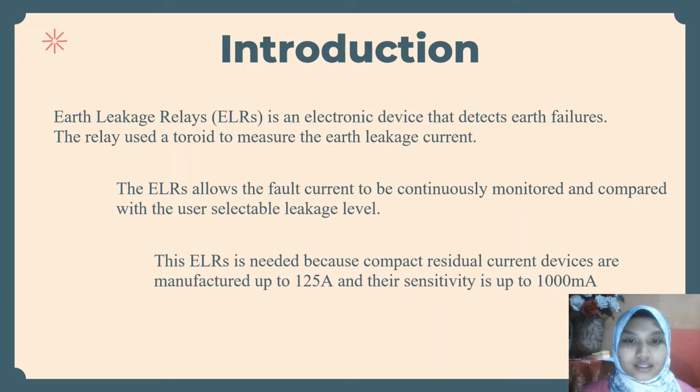This ELR is needed because compact residual current devices are manufactured up to 125 ampere and the sensitivity is up to 1000 milliampere. So the earth leakage relay can be used in circuits carrying higher currents.